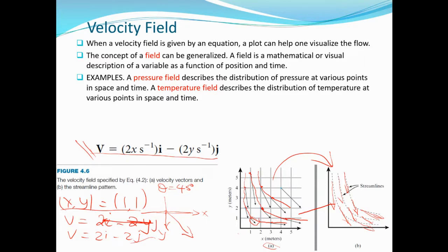We demonstrated this using the velocity field because, like I said, velocity is one of the most important parameters affecting fluid flow. If we look at pressure, pressure is changed by velocity, one way or another. If we look at temperature, although temperature affects the velocity of flow, because when it increases the viscosity reduces, and then the velocity could increase depending on other factors, like I said, we'll be using velocity as an example.